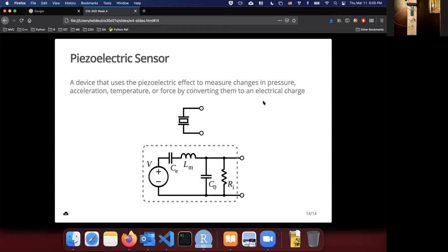So the piezoelectric buzzer is an output device: you give it electric charge and it makes a sound. We can also make an input device, which I just mentioned. We're not really focusing on this, we're probably not going to study it in detail, and we don't even have this part in the kit, but I want to mention it together with the piezoelectric buzzer. You can make an input device, which is the sensor, that gathers a physical property of the environment and converts it to electrical charge so you can measure certain things in the environment.